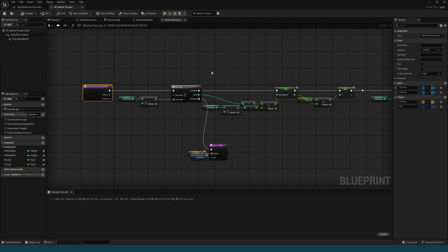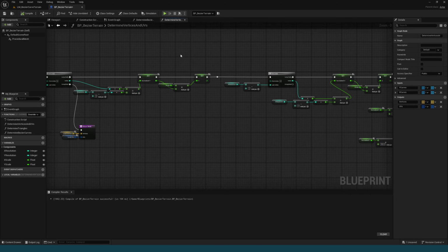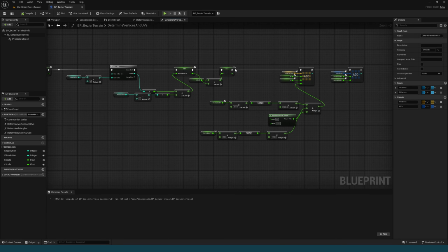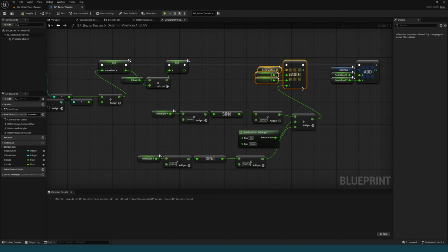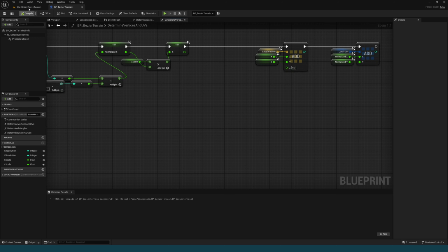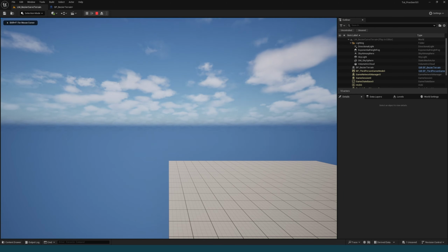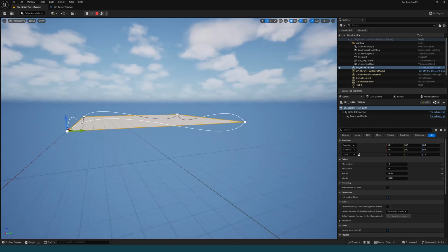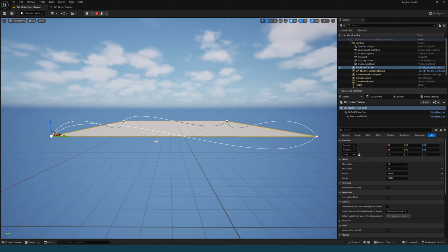Now currently, from the just generate plane with some varying heights, which is what this is doing for our vertices, we are looping through all of our x's and y's to set our vertices along those x's and y's with some randomized height value. Let me delete this randomized height value. Now if we hit play, we'll see we just have a flat plane and our Bezier curves on the edges. Now let's go ahead and try to get our plane to match these curves themselves.